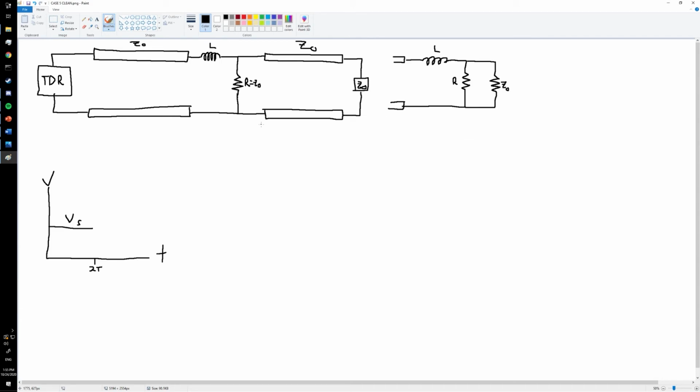For our last case, case 5, we have the same setup as case 4, except our junction is a little different. Instead of our initial resistor, we now have an inductor, and where our capacitor was, we now have a resistor. Once again, the reflection coefficient off of the source, TDR, is 0, and the reflection coefficient off of the load is also 0 due to its impedance matched nature.